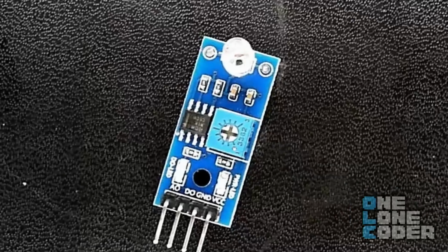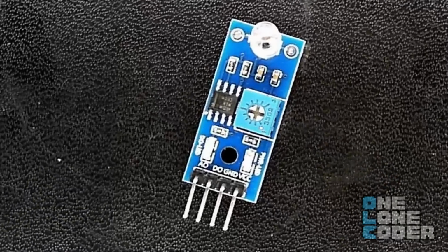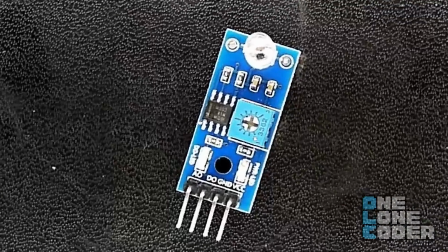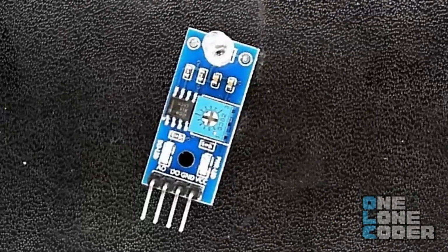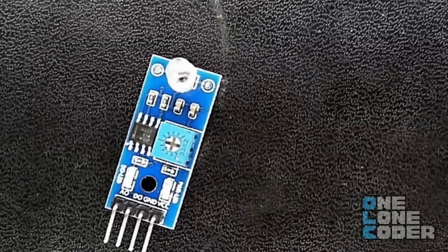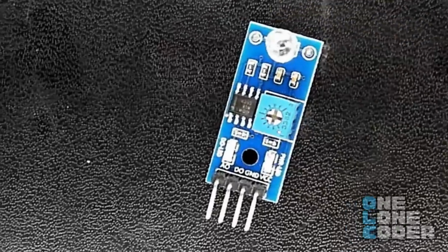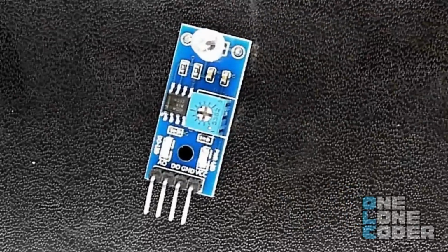And this is it. It's a tiny PCB with a photodiode at the top, some biasing resistors and some capacitors, and a comparator. The comparator will output a digital signal if the light shining on the diode is above a settable threshold set by that small pot that's on there. The thing is also powered by 3V3, and it can output an analog signal too if we're interested.